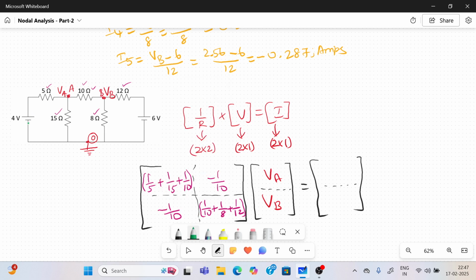Here there is no current, right? So you want to convert into a current first. Normally, the practical voltage source should look like this: a voltage source in series with a resistance. There should be an internal resistance available. This is the practical voltage source. Now, you can convert a practical voltage source to a practical current source or vice versa.